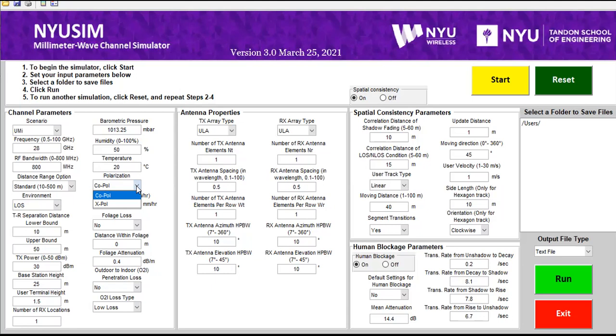So cross polarization can also allow you some signal reception, and you may want to check it for some reasons. You may not have good control over your receiver position, so you may want to check when you are not holding it with perfect alignment. How would the signal reception then be? You may just want to know.